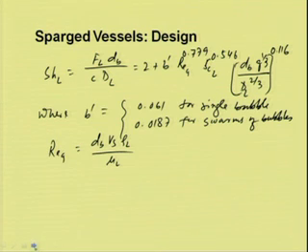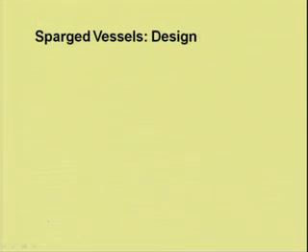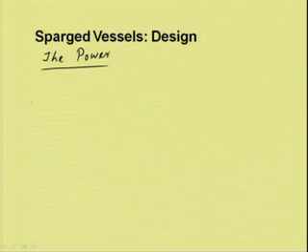Now, we can calculate the power. We can apply Bernoulli's equation between two locations, and we can calculate the power required, which is a mechanical energy balance equation.